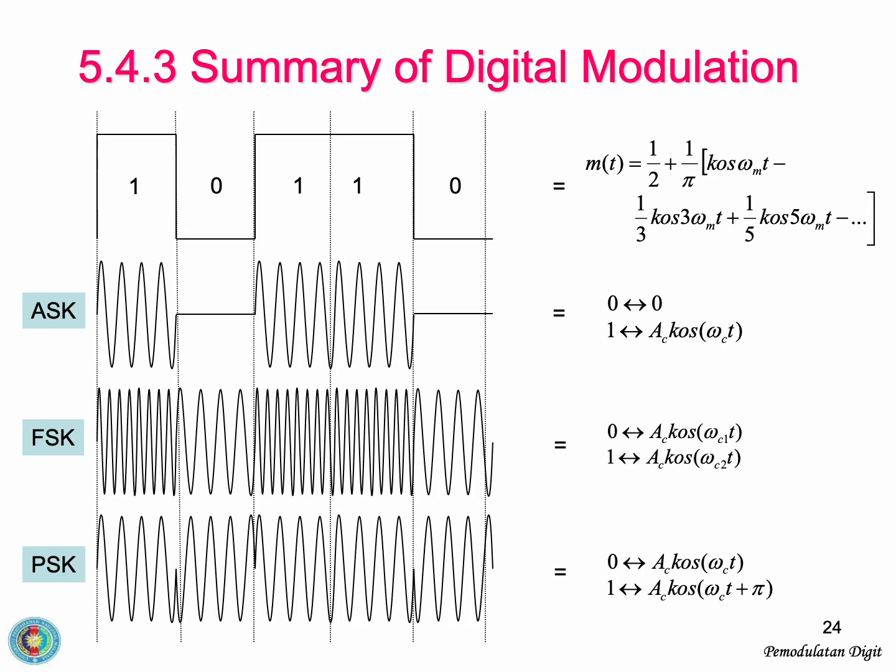To briefly summarize the 3 fundamental digital modulation techniques we've covered, ASK varies the amplitude of the carrier. FSK shifts the carrier frequency between 2 distinct values. PSK changes the phase of the carrier, typically between 0° and 180° for binary PSK. This table provides a concise visual overview of their behavior.